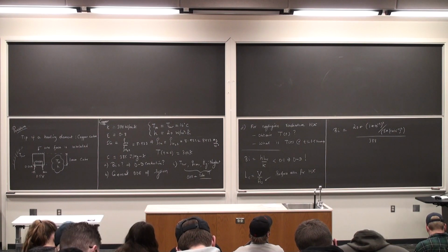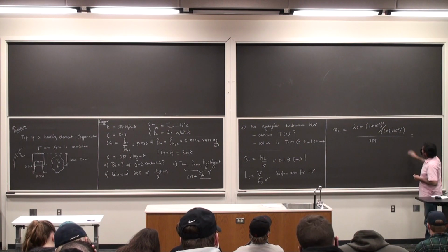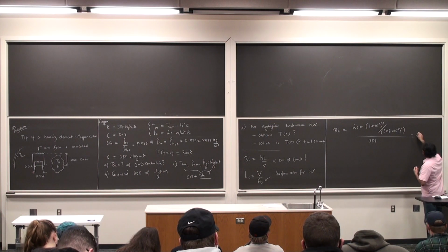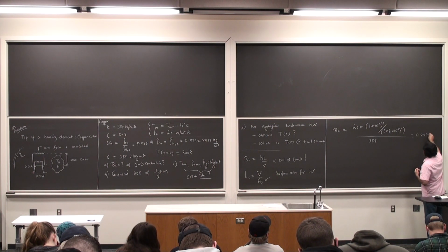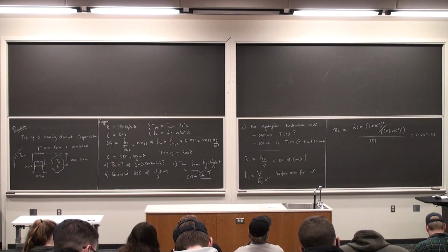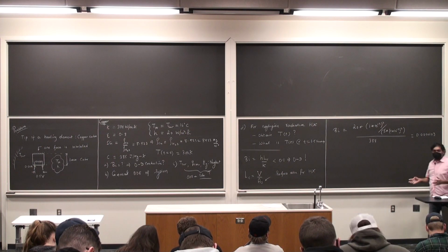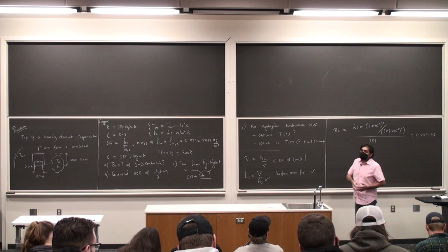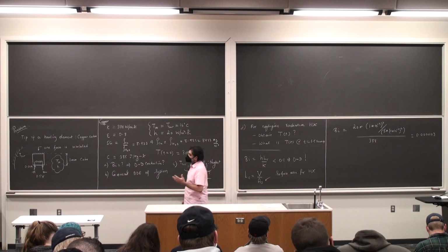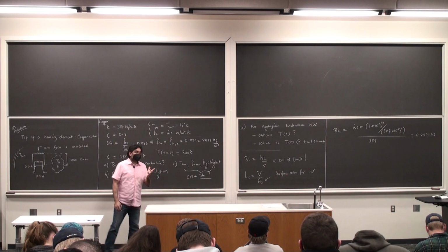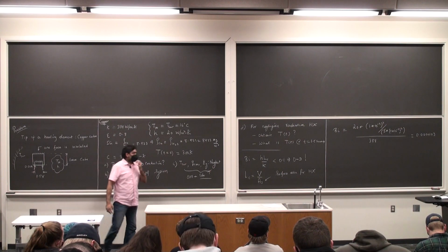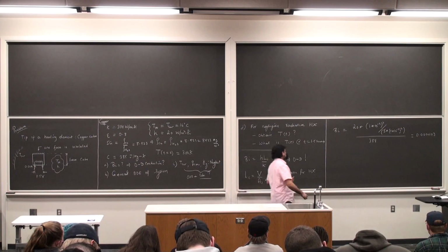You crunch these numbers, it will end up being very small. It's 0.0000103, which obviously tells us that this is a situation where I can assume zero-dimensional conduction. Okay? So it is essentially as if the temperature gradient within this cubic body is negligible. Right, so this is less than 0.1.